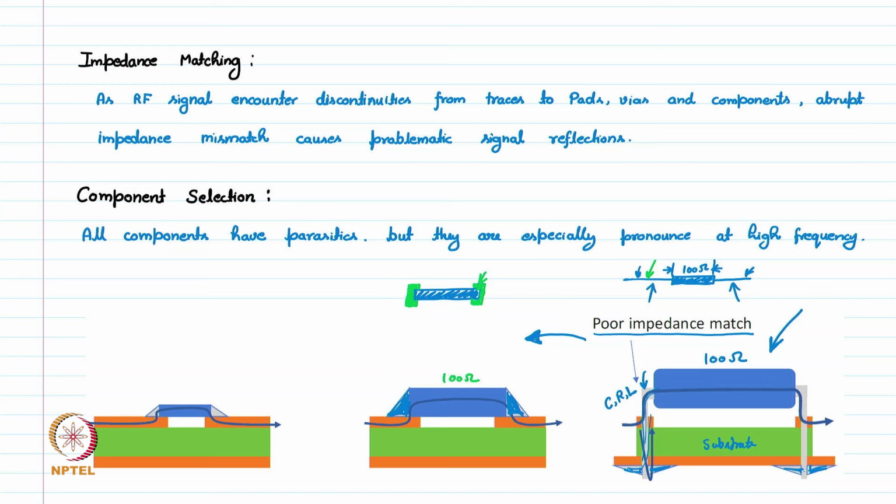However, still if the frequency is very high, then even this much amount of solder can create extra parasitics, the fringe capacitance from this solder to the neighboring ground plane. This is also sometimes unacceptable. So, we can go even to a further improvement in this. We choose a resistor which is very small in size and thickness.